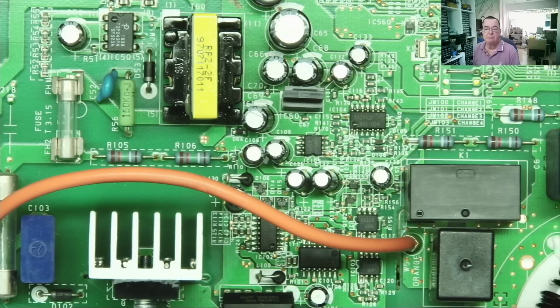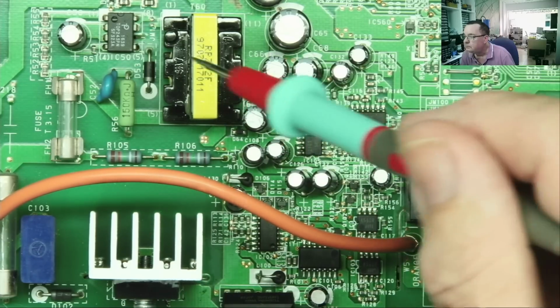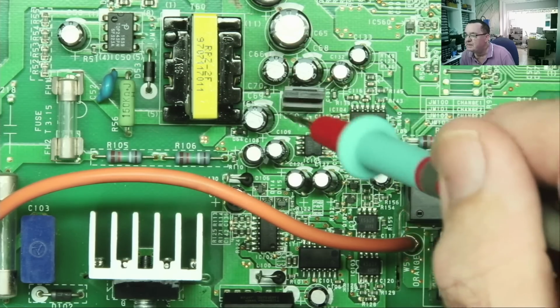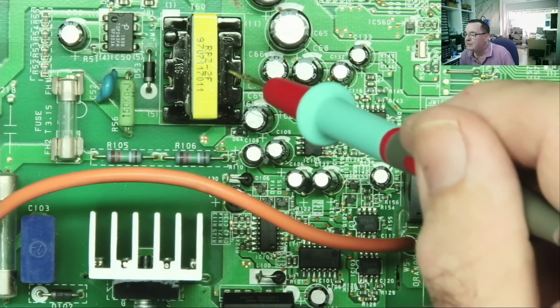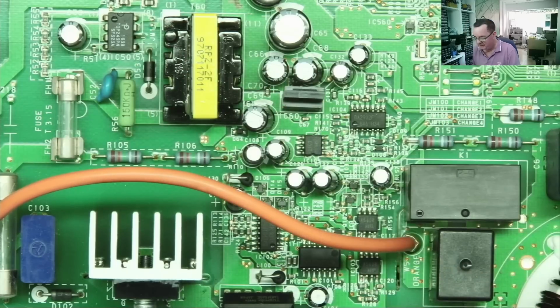I may be able to solve one of the mysteries at least, and that's the low voltage on the minus 15. Because I have my light bulb current limiter in, it's a 65 watt bulb and it's fairly bright, so it's reducing the voltage a lot that's coming to this. It's possible that this supply is more efficient generating the positive than the negative. This is like a flyback type supply, so it may actually generate the correct positive voltages with a lower input voltage than it will the negative.